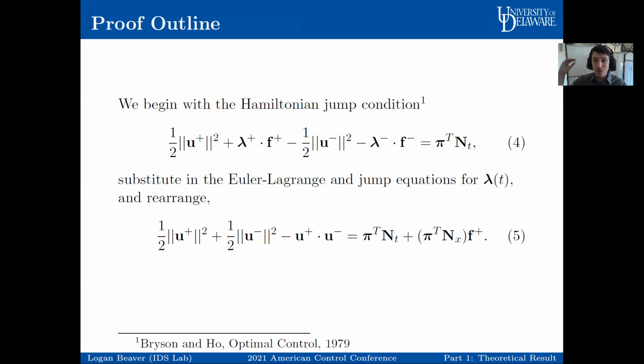So we're taking these q derivatives, and we're using the last one to generate what the control input looks like when the constraint is active. And so we take the q minus 1 derivatives of g and g itself, and we just stack them up and put them in N. So N contains g, g dot, g double dot, all the way to the q minus 1th derivative. And then the subscript t is just the partial derivative with respect to time.